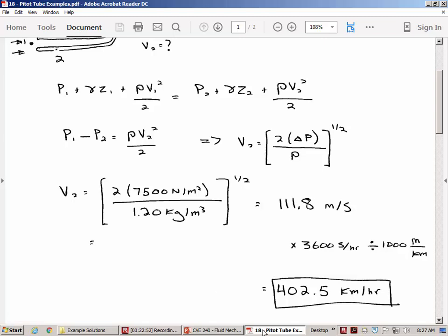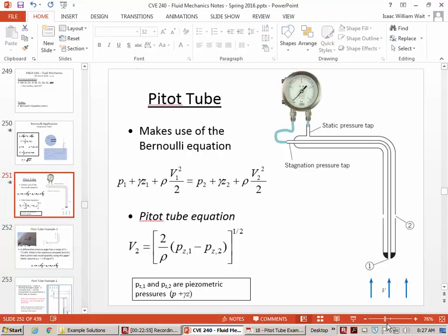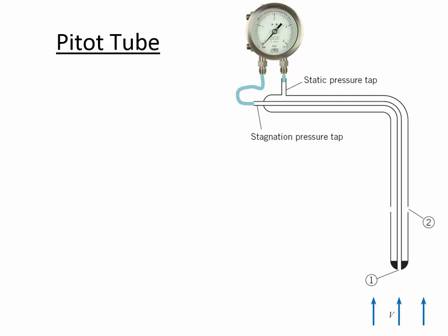Let's go back to the picture of the pitot tube. In this pitot tube, the center opening is measuring the stagnation point, and it goes all the way. If you follow the maze, the opening, which is the high pressure port, is going this way, and then we're continuing to follow it. So here is one end of the differential pressure gauge, and then the static pressure tap, which is opening to the side, is surrounding the stagnation pressure tap, which is the center one.